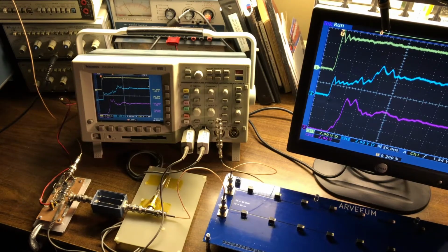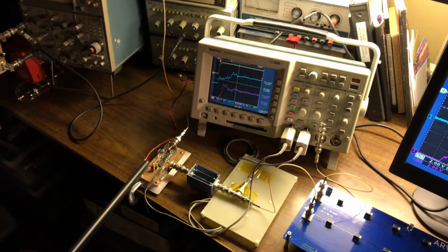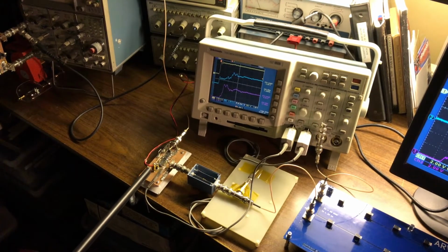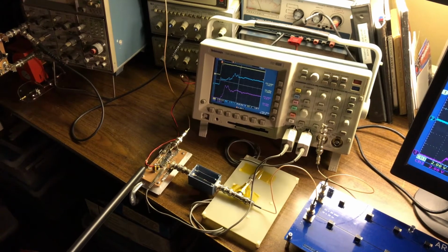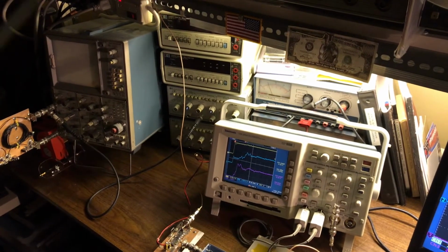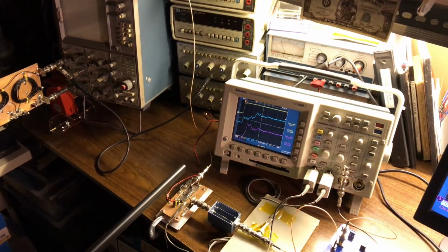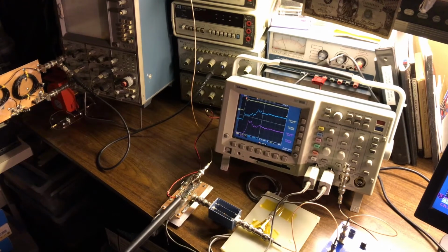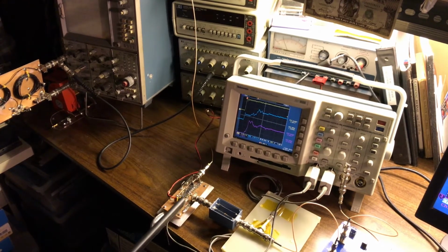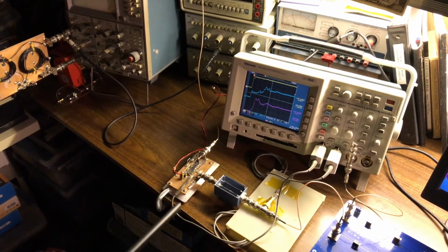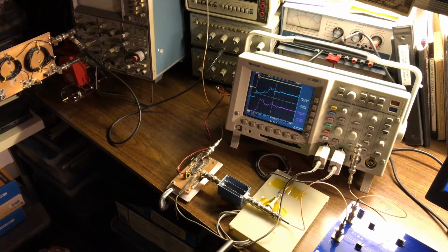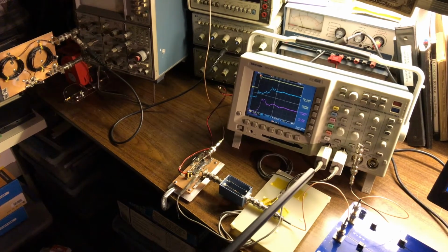This is the experimental setup. This is the low impedance driver implemented with 74AC04 packages. Signal is fed to it from a pulse generator down this coax cable. Right at the output of the low impedance driver, this probe taps this signal to be displayed in